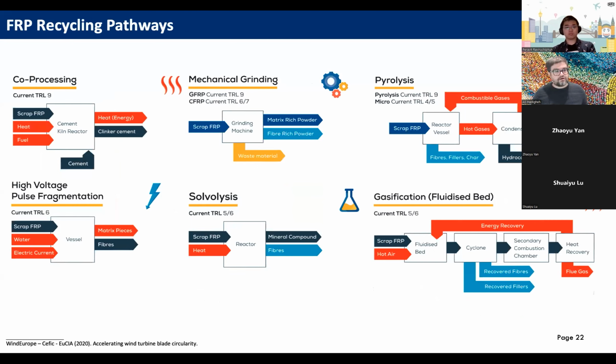So, having said that, there are few methods for recycling of FRP composites. They all have advantages and disadvantages which should be considered when a recycling process is designed. So common methods are the pyrolysis process and mechanical and repurposing processes. Pyrolysis, if you are not familiar with that, is basically a thermochemical method to recover clean fiber from polymer composite waste within oxygen-free conditions.